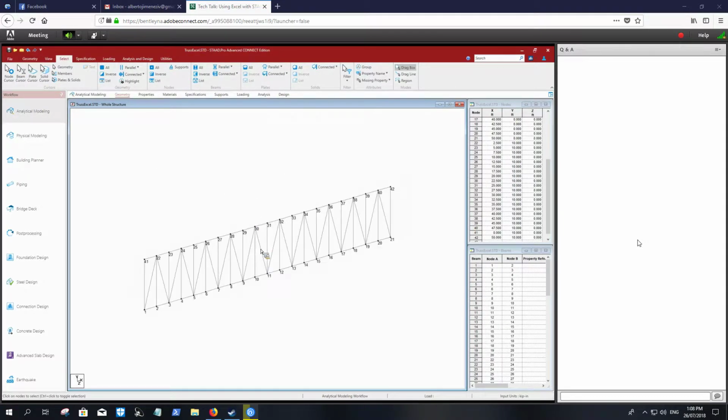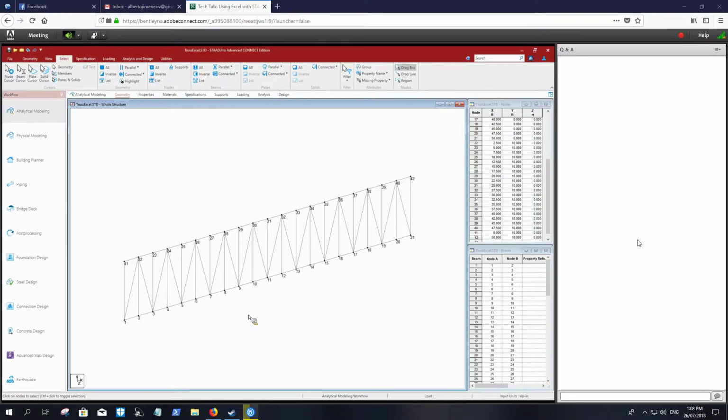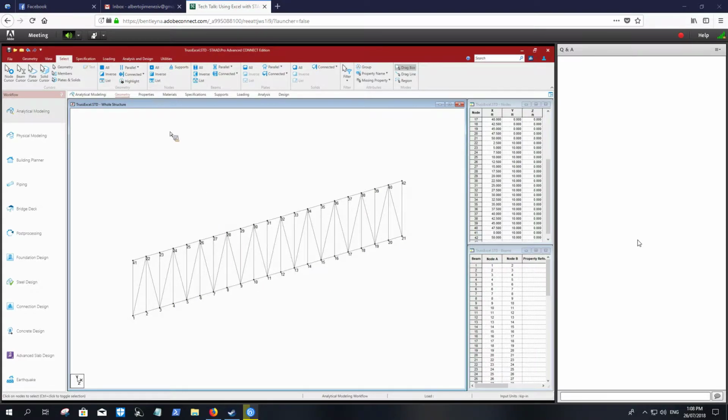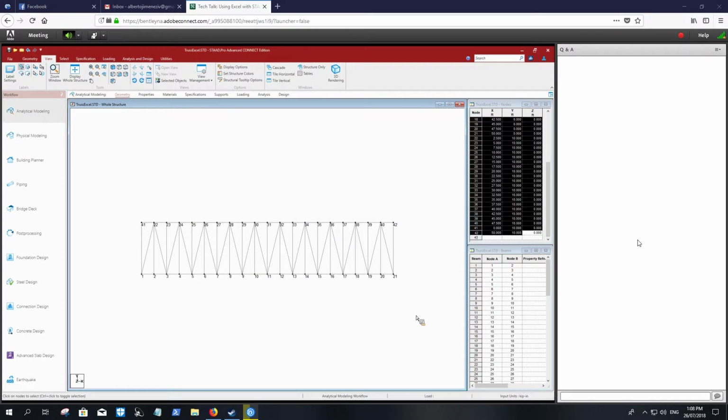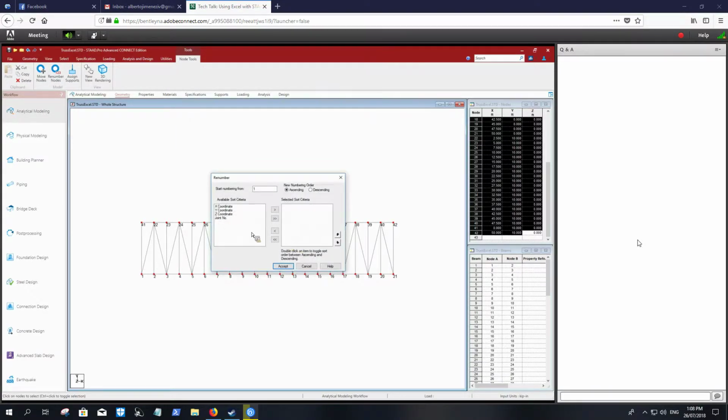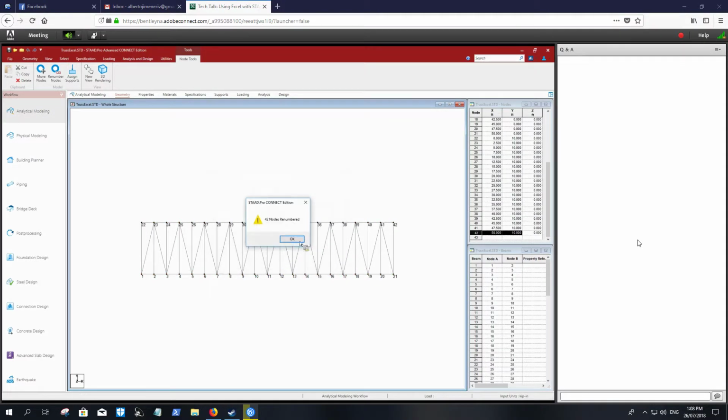Okay, very good. So we're nearly there, but because we're dealing with formulas in Excel, it would be nice if they're sorted, because I added these nodes in, right? So what I can do is sort these nodes. I'll go to View, Front View, select these nodes on screen, Node Tool, renumber nodes. At first I want to sort by the y-coordinate first, and then x. I'm going to hit accept. You're going to watch this 41 change to 22. So now it's nicely sorted.